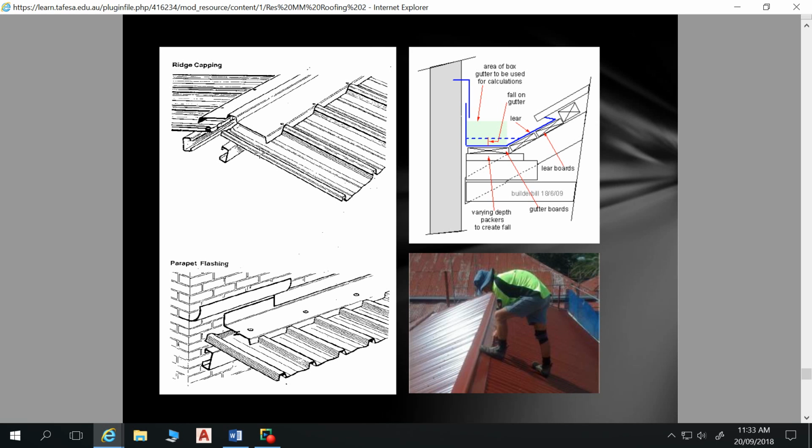So I'm saying, rather than have Hebel that goes all the way up and you notch in and you're cutting in, I think it's better to actually have a Hebel joint there and carry your flashing inside to fit. Because if you're just notching into your Hebel, then you're relying on that mastic sealant to bind with your Hebel and your flashing. Stuff doesn't bind to Hebel all that well.